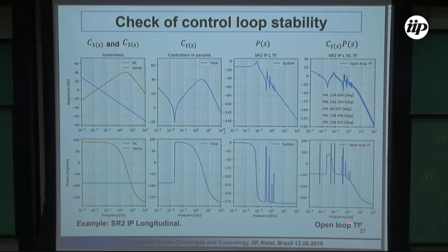That means you need to study the open loop transfer function and see whether, when this product is 1, it has 180 degrees of phase shift or not. These are parameters, for example, this is the phase margin. So you can say how close or far away this system is from instability.